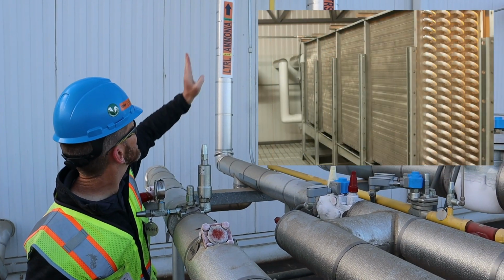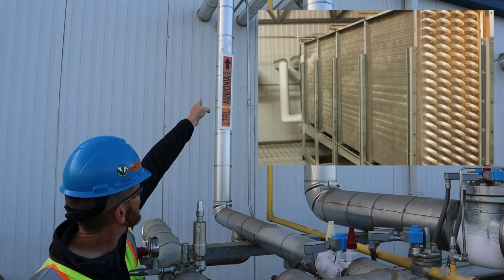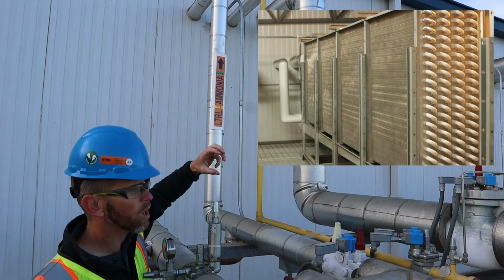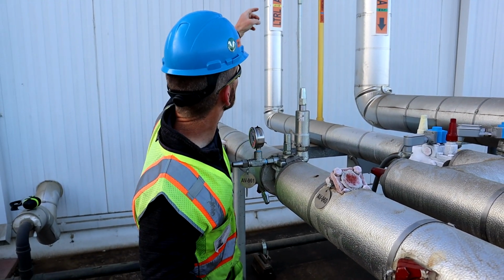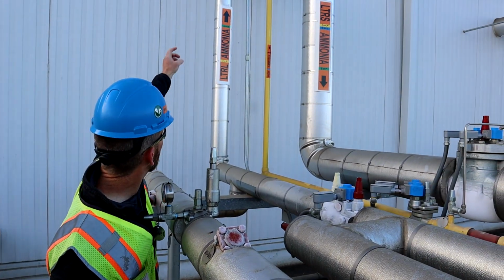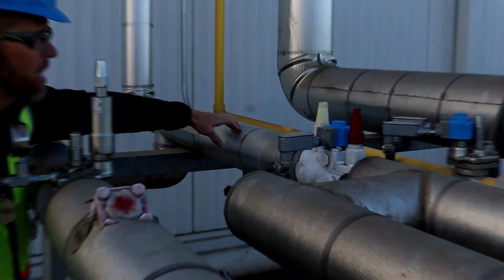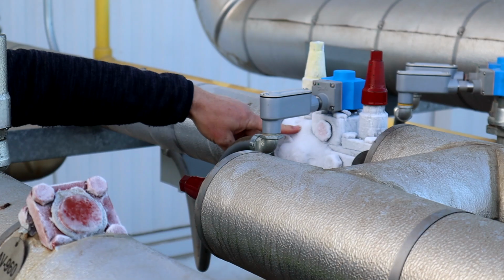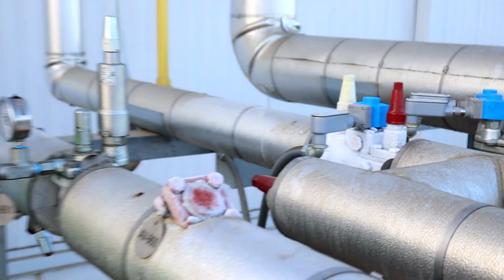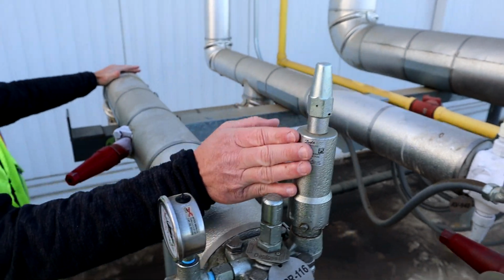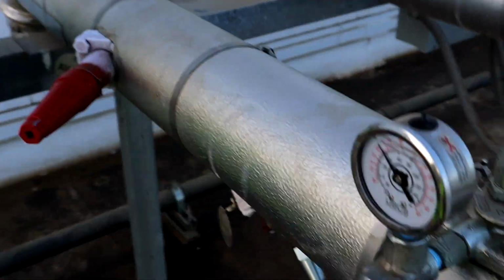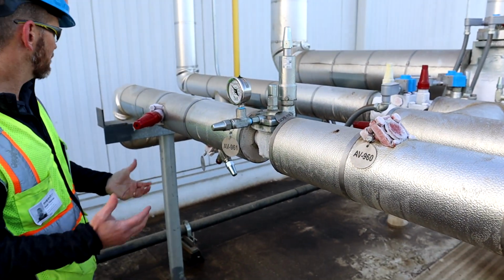Inside the room, we can't see here, but that pipe enters the room and then it flows through the coil backwards. Instead of going through the liquid, it's going through the suction pipe and exiting through this liquid pipe. But because of the check valve in here, it can't go this direction, and it's forced now through this route here. And this is our defrost condensate regulator, which has a set point of 70 or 75 psi.